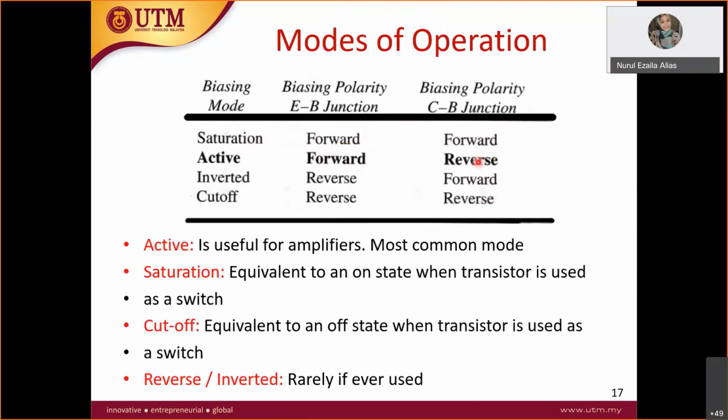So it has three modes of operation. If you want to make it active, you have to connect base to emitter forward bias and base to collector reverse bias.